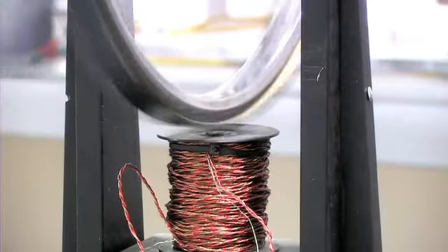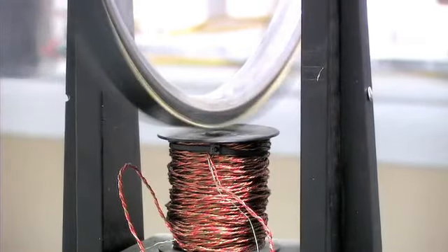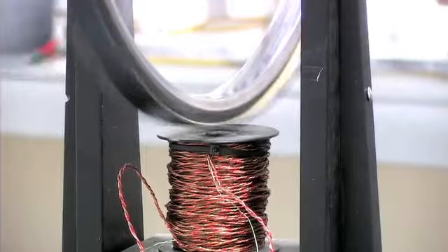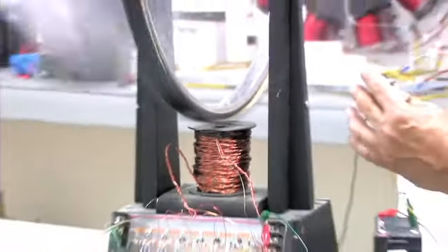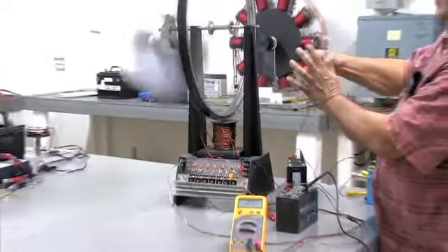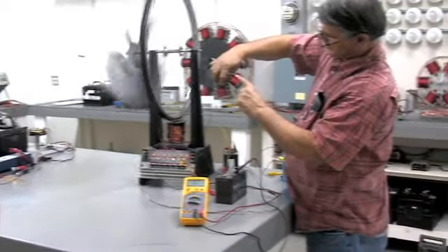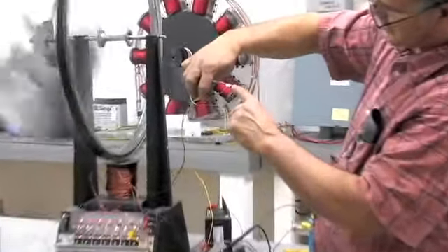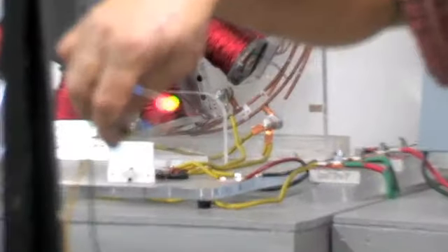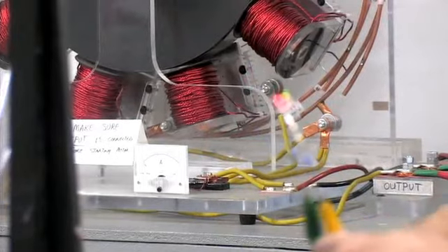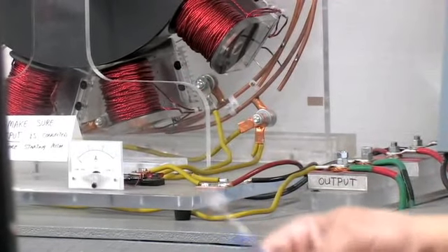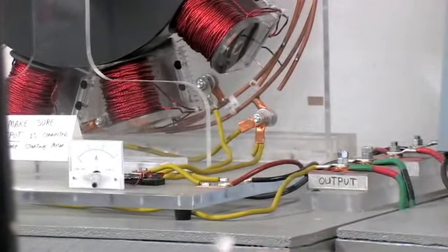See, and so you can make a simple set of timing lights by using two LEDs back to back and a couple of resistors so that you can see the firing across the coil. You can see one is the charge and one is the discharge. So that's one way you can do it, to find the exact timing.